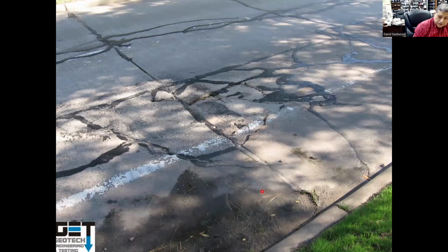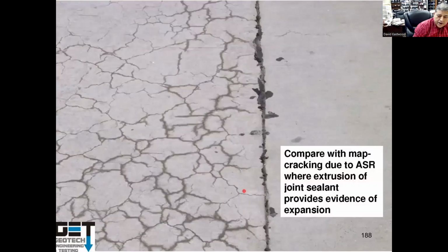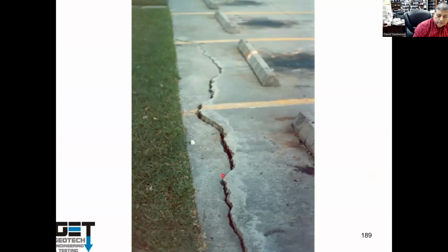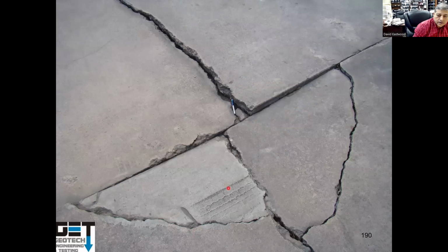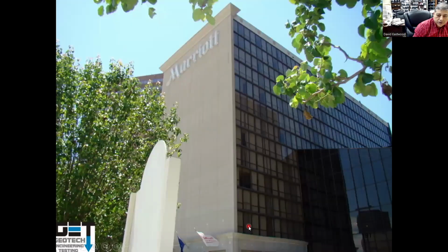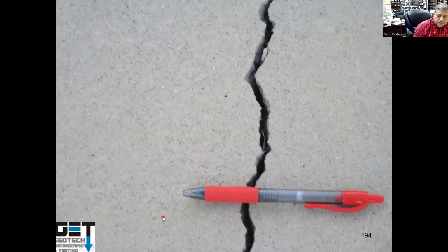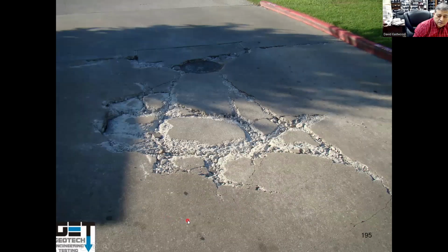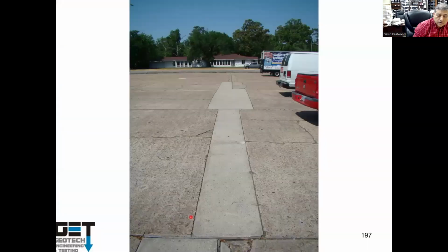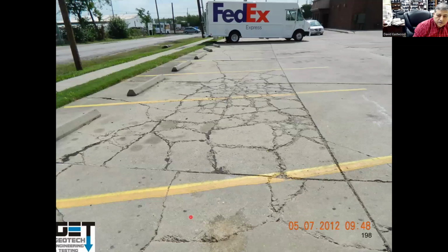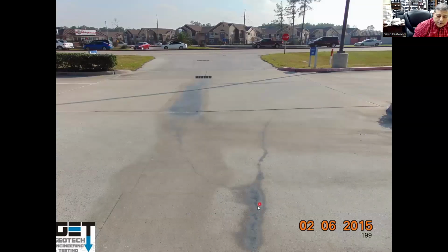Concrete pavements, we see a lot of pavements with distress. A lot of concrete, you got alligator cracking out there. No steel in the paving. This is the paving out there for the Marriott on West Loop. Joint failure. A lot of these expansion joints fail, starts pumping. Cracks in the paving itself. The shrinkage cracks. All kinds of weathering and pop outs. You can see the cracks in the paving all over the place. Concrete paving. The black stuff coming out through the concrete is all the soils that's seeping through the subgrade into the pavement areas.